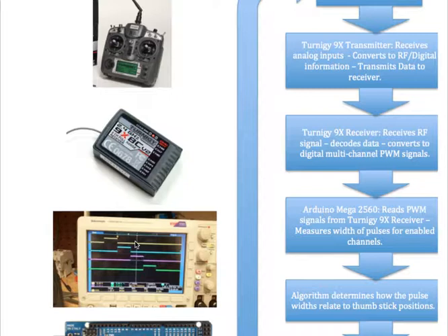When we think of channels, a channel is say one axis, so thumbstick up or thumbstick down for the left thumbstick, that is one channel. Thumbstick left, thumbstick right for just the left thumbstick is another channel. So on a thumbstick you have two channels. We have two thumbsticks, so there are 4 channels, and then there's one button, so that's our 5th channel.